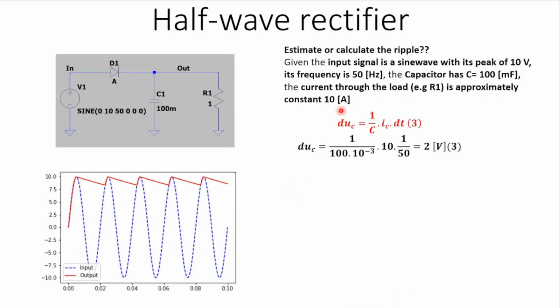And here, if we look at the rectifier signal again, the value of the ripple is here. So the value of the ripple can be calculated in either process. We can calculate the ripple in the charging process, or we can calculate the ripple in the discharging process. Either process will give the same value of the ripple. This is the value of our ripple.